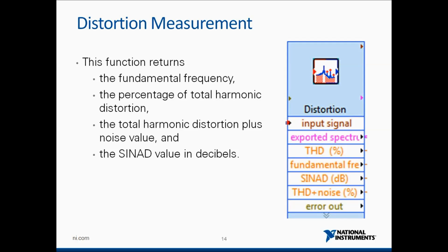So let's move forward. This is what we are going to study, these special VIs that are frequency domain measurement VIs. We have 4 VIs in this palette. You can find this palette in the Signal Express palette. Then if you go to analysis and frequency domain, I'll show you a live demo of that.